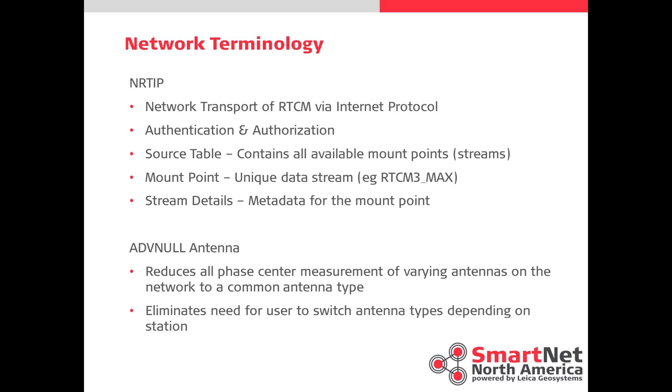Yes, the mount point entry is required. So if you're using something that you have to hand enter a mount point, you can go onto the connection and configuration page of the website, and it'll tell you specifically for your particular rover or brand what mount point and what the mount point name is. So if you want to receive it, that's the extension, if you will. So if you call in via NTRIP, the mount point would then be the extension so that you get a hold of what you want to get a hold of.